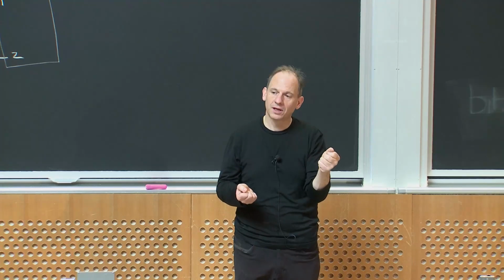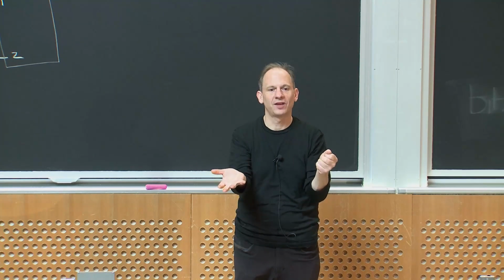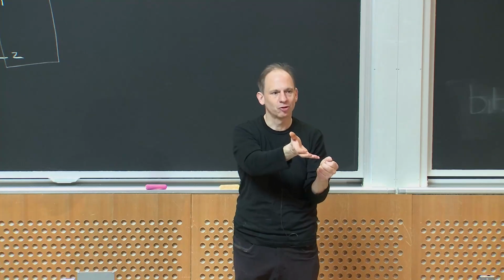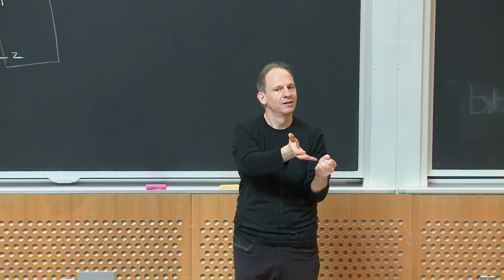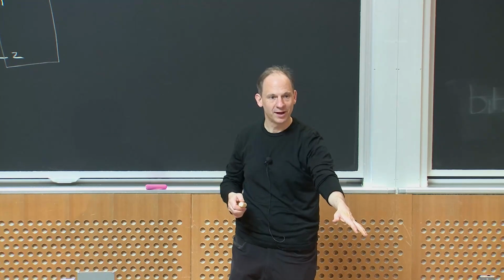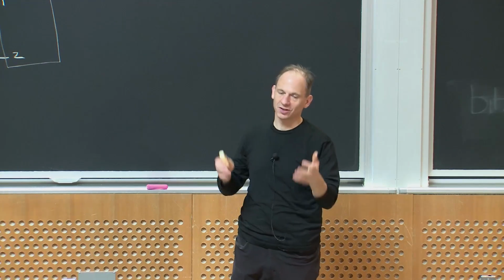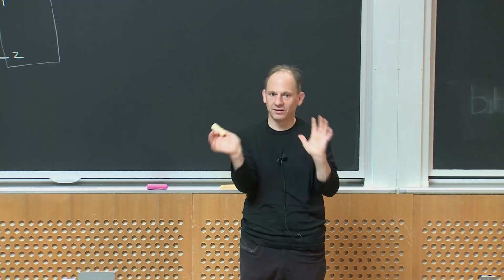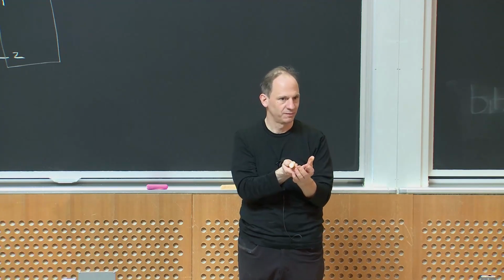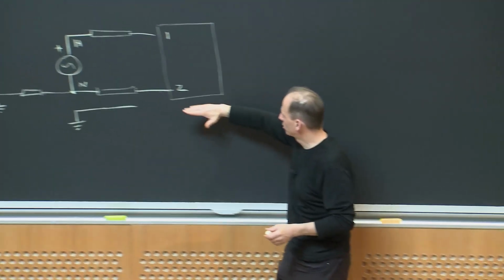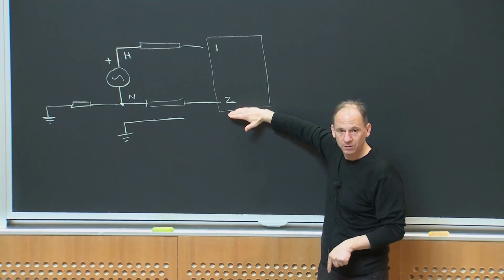Why? Because suppose there's some fault inside the equipment, and that fault shorts the hot terminal to the case. You don't want somebody walking up and touching the surface of that thing and getting electrocuted, right? So if they ground the case and some fault happens inside, huge current will flow, it'll blow the breaker, and then things will be disconnected and you'll be safe. Okay? So very often there's an explicit connection between the case of the device and ground.